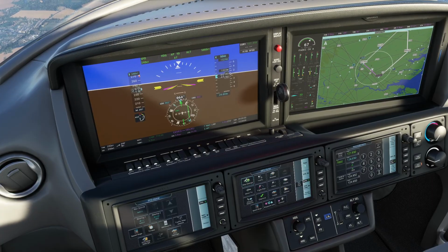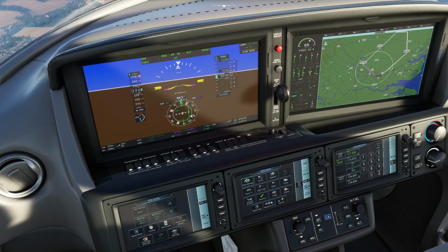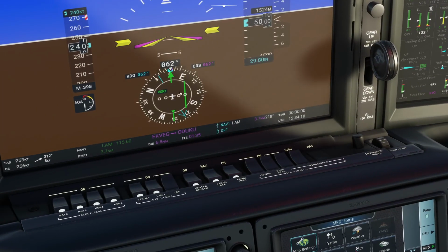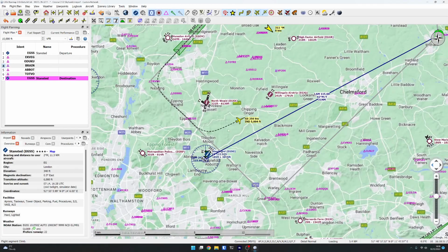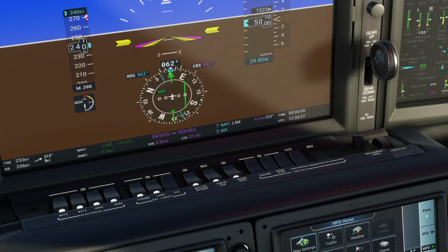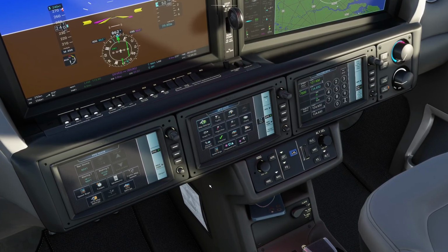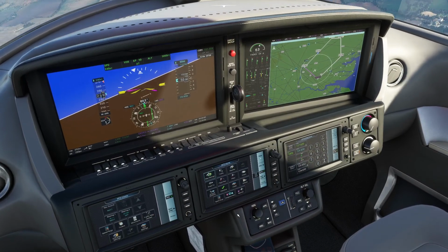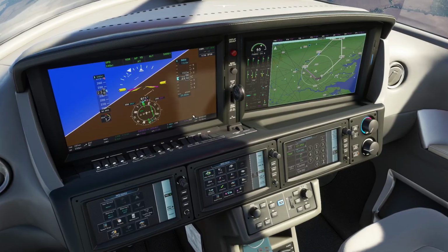So you can see we are to the left of the 62 degree track from the VOR. So from means this little green arrow is pointing behind us. It means the VOR we are tuned into is actually behind us. Yeah, which is true, look. There's the VOR, there's us. And we are to the left of the track. If we go back to nav mode now, the aircraft will crab sideways onto the 62 degree track. But you have to have set your course for this to behave in this way.